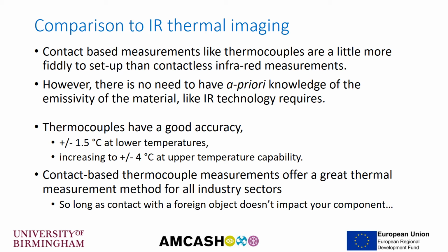Thermocouples have got a good accuracy. They're quoted as plus or minus 1.5 degrees down at lower temperatures, increasing to about plus or minus 4 degrees up at the higher temperature capability that they can measure. And contact-based thermocouple measurements offer a really great thermal measurement method for all industry sectors, so long as the contact with a foreign object isn't a problem for your component.